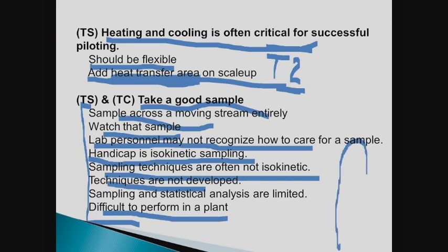Distillation column, dead of winter in Pittsburgh, Pennsylvania. They wanted the vapor stream from the top tray. So they went in and had a tap up there, and they collected it in a beaker. 20 degrees Fahrenheit, gale winds, this material froze in the tube. Never got to the collection beaker. So as an example, you may have thought you got a sample, but you really didn't.